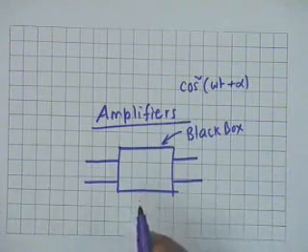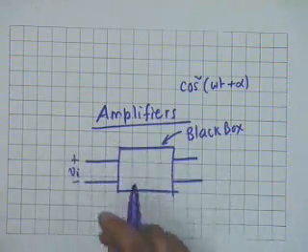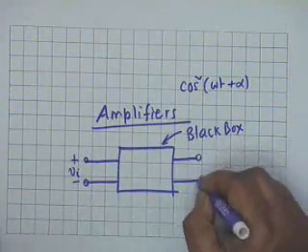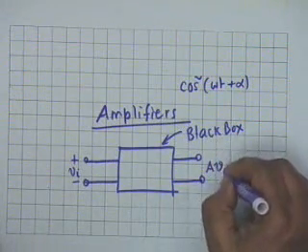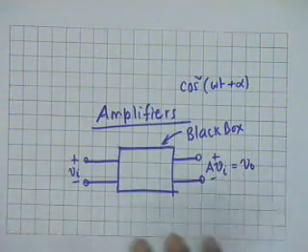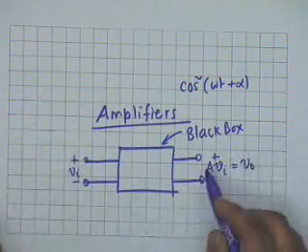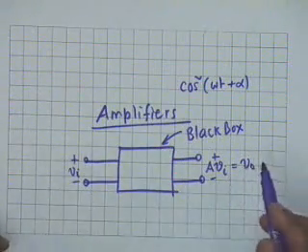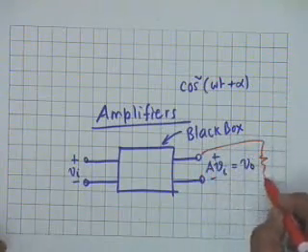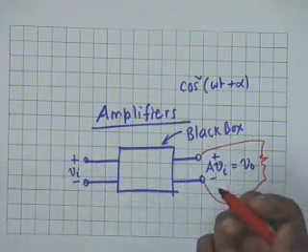And an amplifier can be defined in terms of a black box, such that if I connect a voltage source VI at one of the ports, then at the other port the voltage developed is A times VI. Alright, this is the definition of an ideal amplifier, that irrespective of what happens to the outside world, if we connect a voltage source VI here, an output of AVI shall be developed, irrespective of what is connected to these terminals. For example, we could connect a resistance RL, irrespective of what else is connected here, we don't really care.